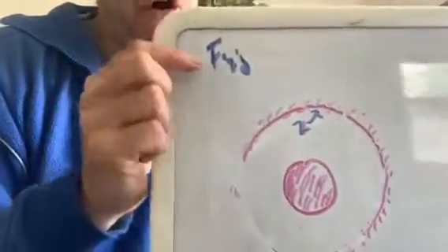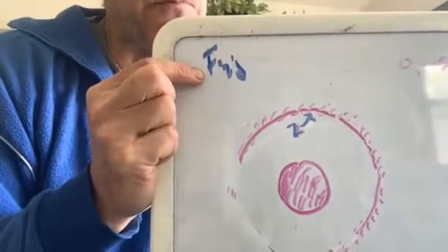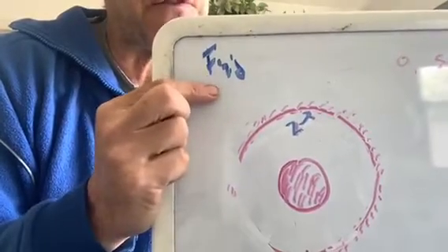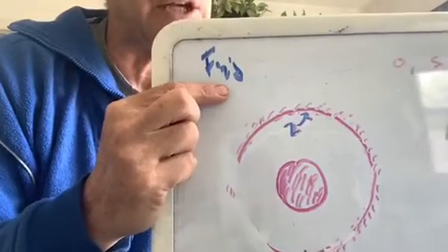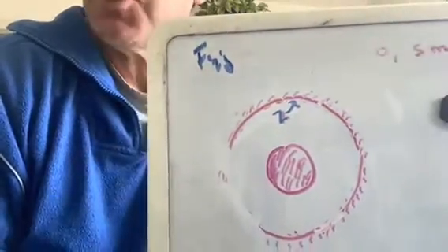Just a quick reminder, a little more thought on that. Doing that involved figuring out radiation view factors, and the common symbol for the radiation view factor is Fij. Fij would stand for the fraction of radiation leaving surface i that hits or reaches surface j.